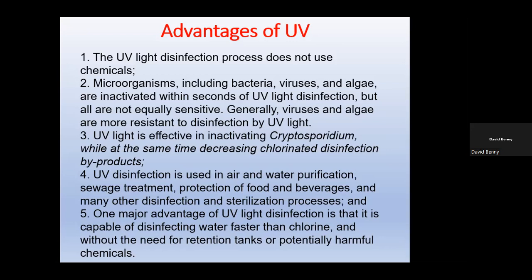It is used in air and water purification and sewage treatment. And one major advantage why people tend to go for UV is that it is capable of disinfecting the water faster than chlorine without the need for retention tanks.